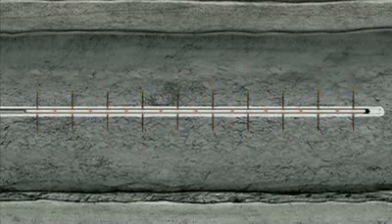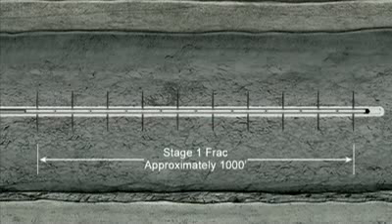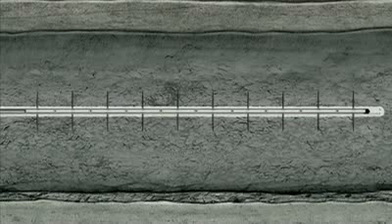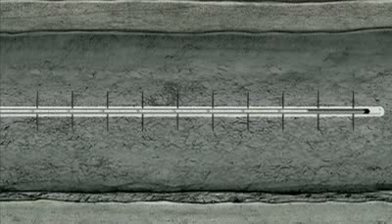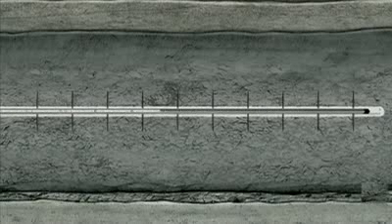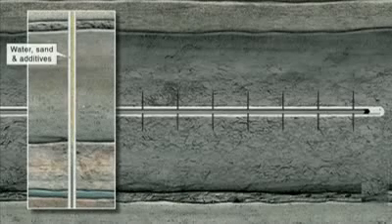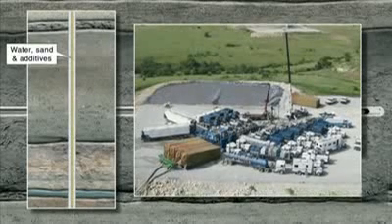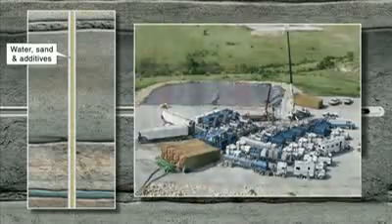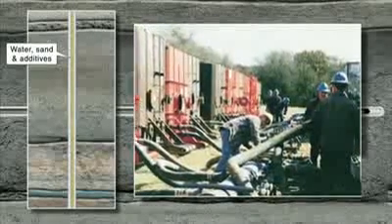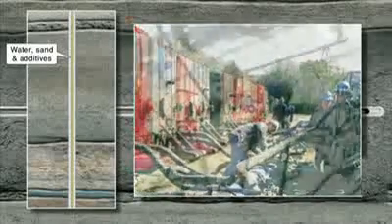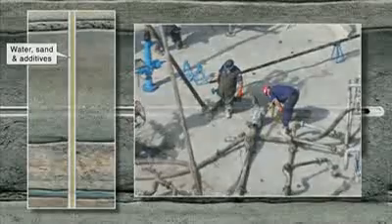This is called perforating. A crane is used to lower a perforating gun down the well pipe on a wire line, several thousand meters to a point along the horizontal section. Next, an electrical current is sent down the wire line to charge a series of small holes through the pipe casing and cement a short distance into the shale rock. At this point, because the gas is held very tightly in the rock, it is not expected to just flow gas into the well casing.